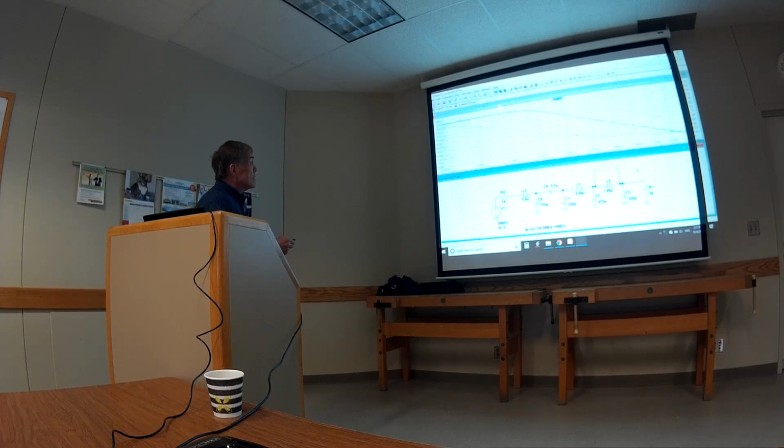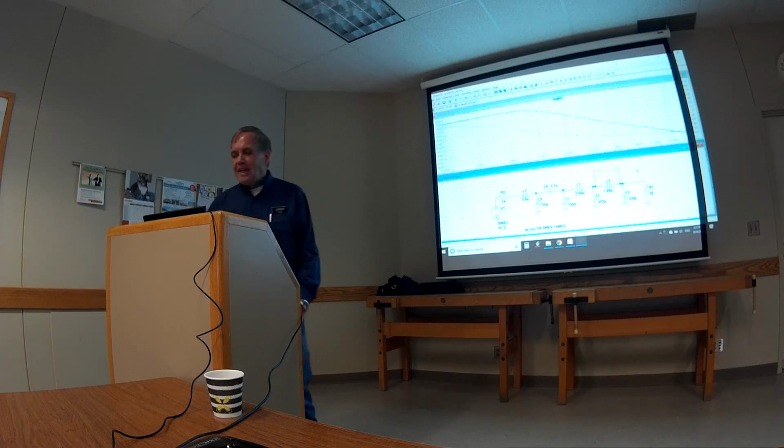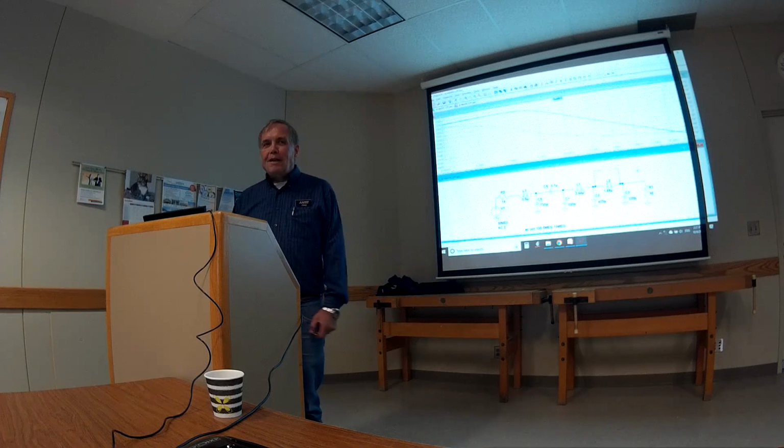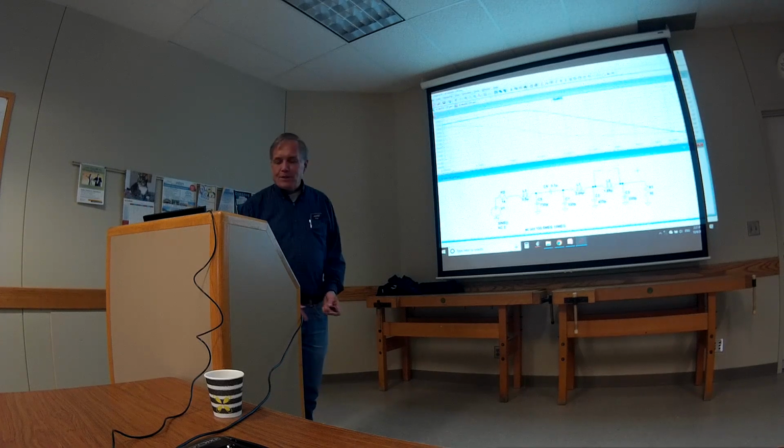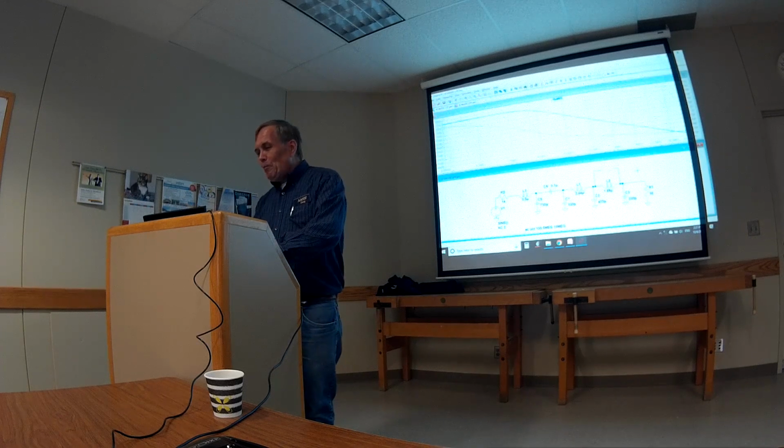Well, 7 megahertz is still pretty good, but at 14 it's 36 dB now instead of 80. So you can see the value of that little capacitor in there, making that notch, it really brought it down. It was very powerful. Sometimes they put multiple sections, on the second or third one, but there are various designs. But this was a very powerful little topology to make a nice low-pass filter, and that's the one I put in the little mini rig that I built.